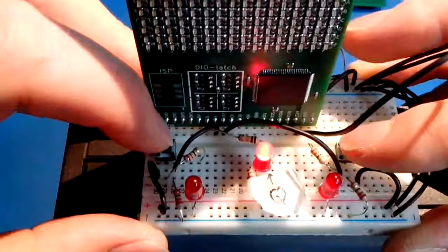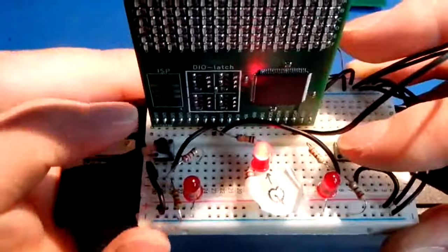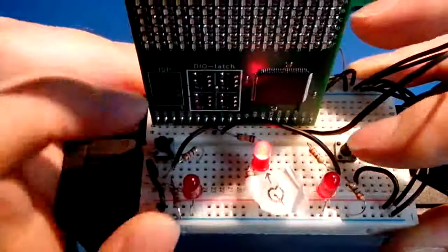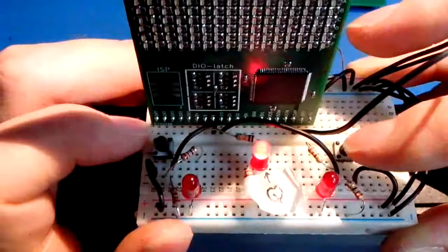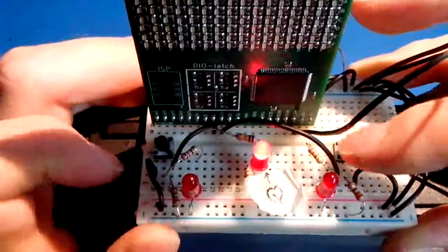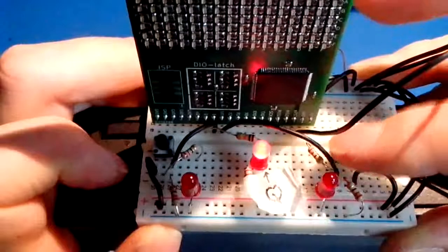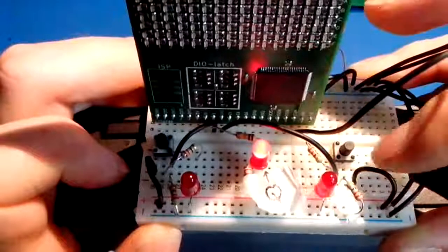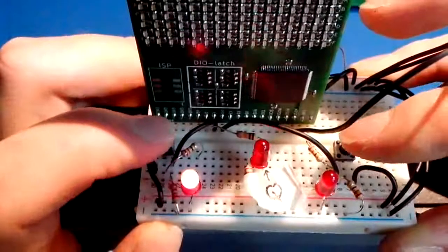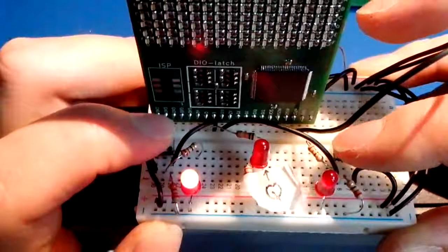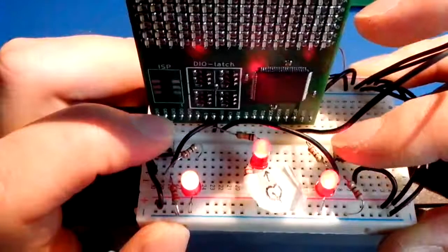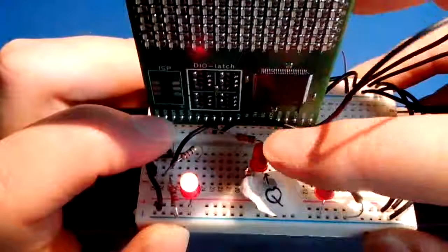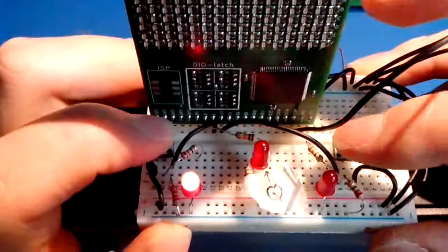Anyway, this behaves pretty much like the 8-bit latch, and now the output Q has a certain value. Now it's on, the value is high. I'm pressing the D button now, so I'm toggling the D input between 0 and 1, and as you can see nothing happens with the output. Whenever I press the E button, so I enable the latch, whatever is supplied at the input, that's the rightmost LED, is copied to the output, the leftmost LED.